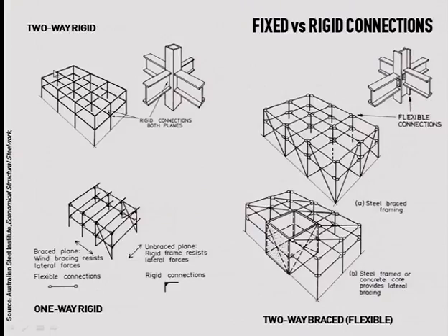Look at these two diagrams. This one on the left and the one on the right. These kind of circles, they identify the release of the joint. So they identify that the joint is flexible. So you see this is just a symbol, a convention to identify that there is a hinge. So this circle means that it can slightly rotate, and therefore bending moment is not transmitted.